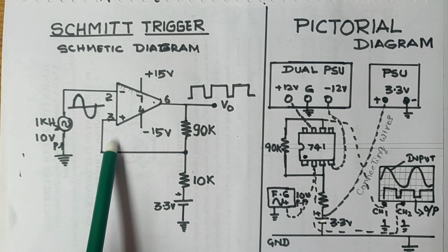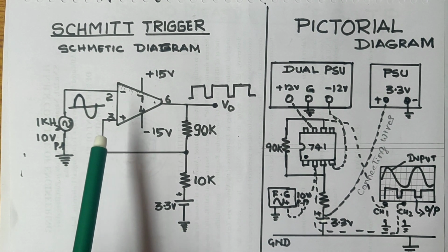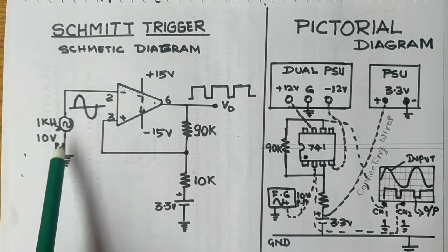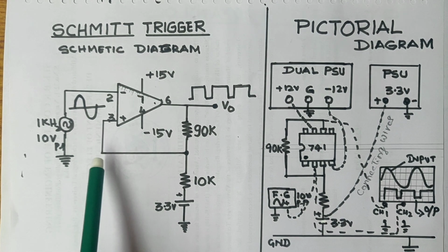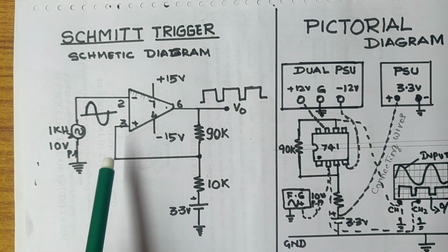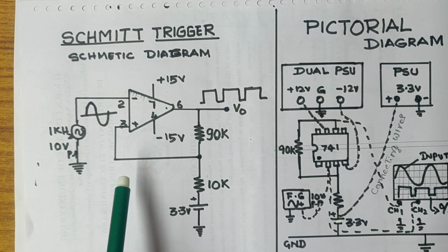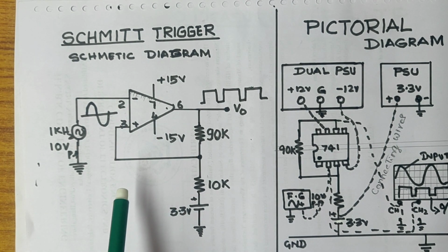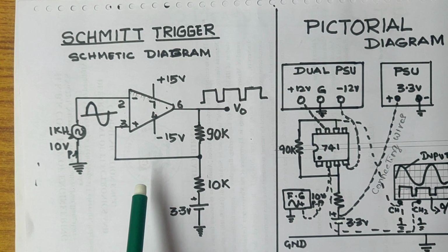First let us see what ST means. That means Schmitt Trigger. It is a regenerative comparator. It converts a sinusoidal input into a square wave output. The output of the ST swings at the upper and lower threshold voltages, which are the reference voltages of the input waveform.